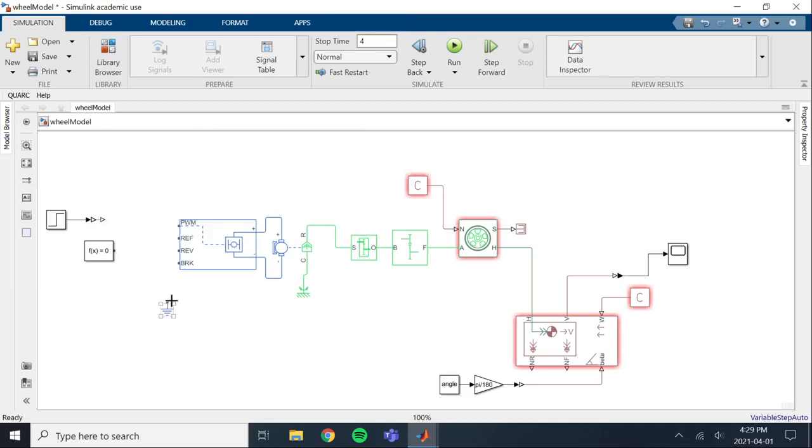So you have to connect all of the components that are grounded to this line. So connect the DC motor's ground. We're also going to connect this import and this import. So for our purposes, this is the brake and reverse imports. You would normally send a signal there if you wanted to brake or reverse the HBridge.